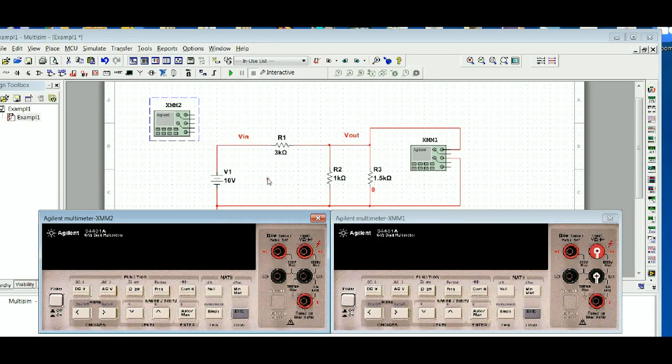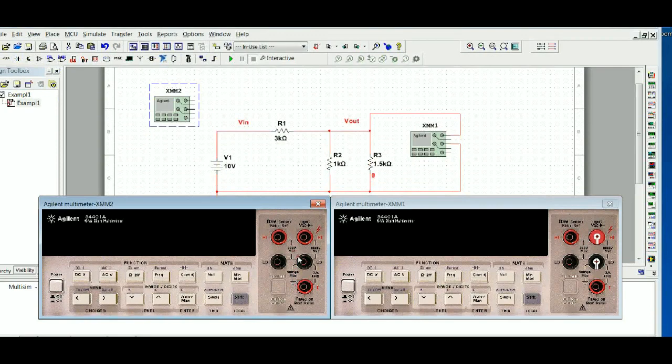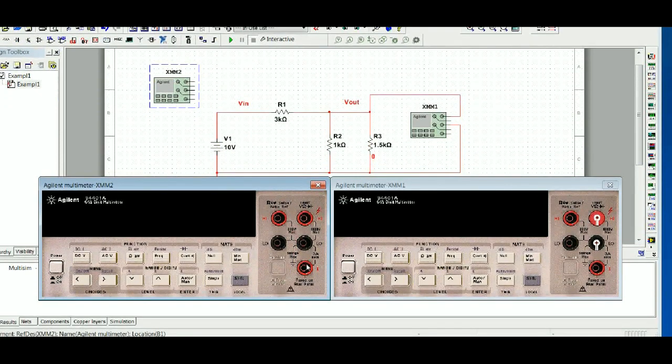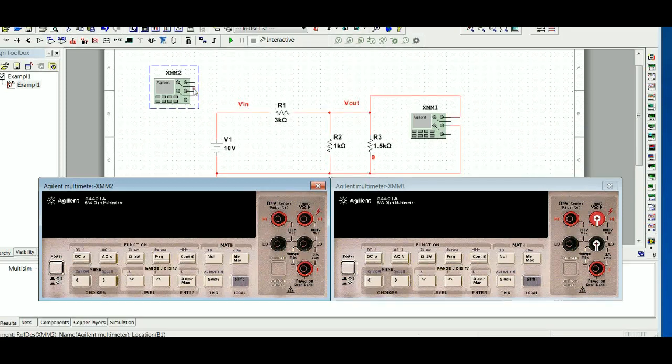Now to measure current, we're going to have to use the center jack, the one that says I on it. And this is common sense from the standpoint of manufacturers, because if you're set up to measure current and you put it across the voltage source, since an ammeter is supposed to have zero internal resistance so it doesn't perturb the circuit, it'll do damage, which in the case of our meters will be to blow a fuse. Yesteryear you could destroy a meter. So I'm going to be using these two here, which would correspond to this wire and this wire.